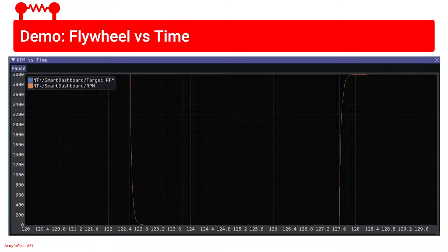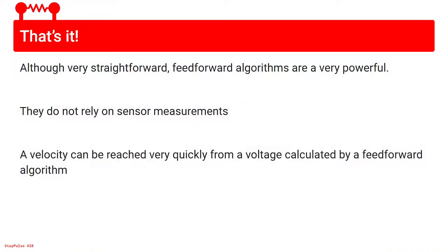And then also for feed forward, if there was a different kind of error, like more friction, that would cause it to stop working, right? Yeah, if there was a non-constant friction term, you would need to account for that. But we'll learn about an algorithm that will react to that. I'm just gonna put PID on the board in a second. If we had unexpected errors, we could use a different type of algorithm that's reactive to error instead of only reactive to set point.